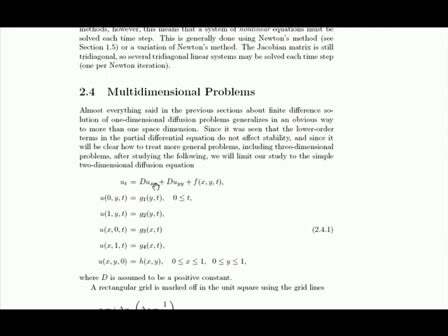And we're going to give the temperature on all four sides of the square for all time, and the initial temperature in the entire plate. Those are the appropriate initial and boundary conditions for this method. Again, we can use implicit or explicit.